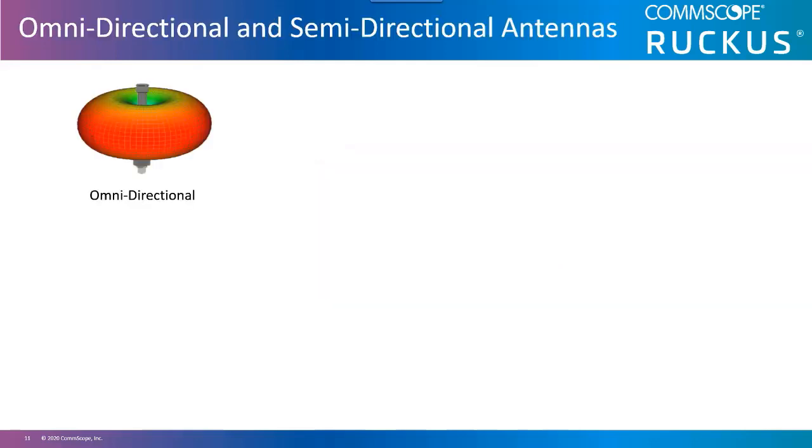Omnidirectional antennas are only omnidirectional in name. The small rubber dipole antenna is an example of this type of antenna. It is the default antenna of most external antenna access points. A perfect omnidirectional antenna would radiate RF energy like the sun radiating light in all directions, just like we spoke of the isotropic radiator earlier.